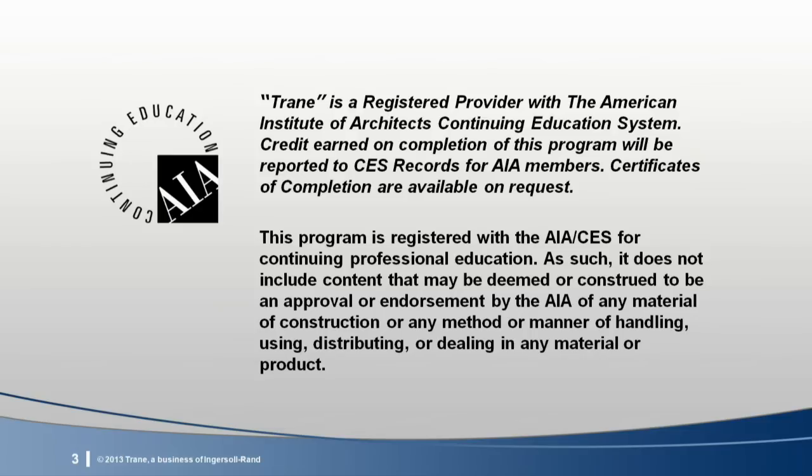ASHRAE Standard 62.1 is titled Ventilation for Acceptable Indoor Air Quality. It specifies ventilation rates as well as system design, construction, and operating requirements that will provide acceptable indoor air quality. It's the basis for many local building codes and is a prerequisite for LEED certification.